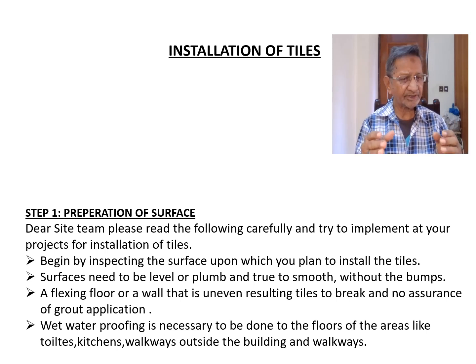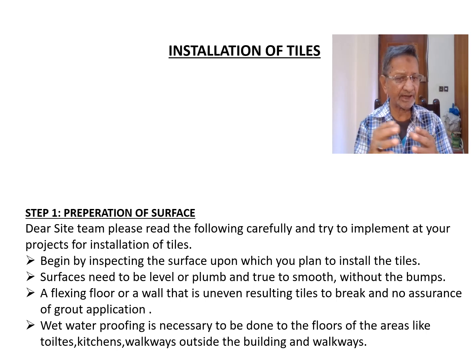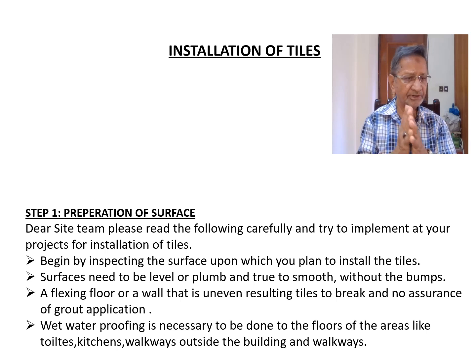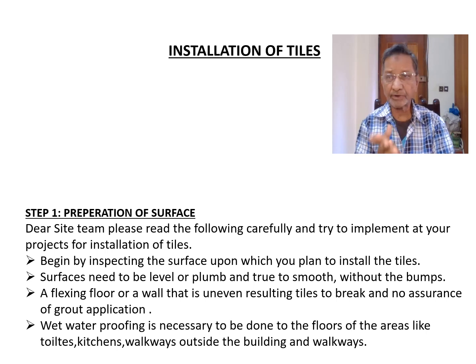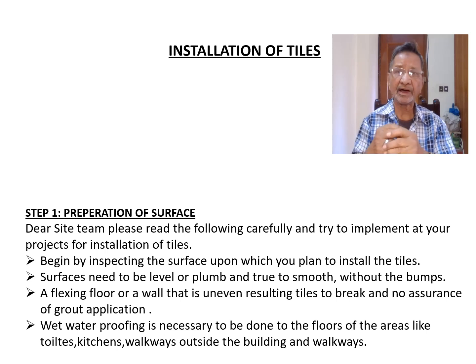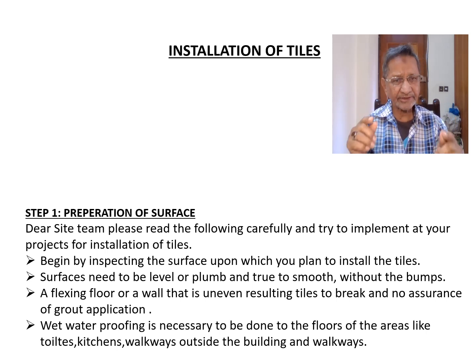If the floors are in high moisture areas like bathrooms, kitchens, and outdoor walkways, which are always wet areas, in these areas you have to arrange waterproofing so that water and moisture should not seep or leak through the joints.